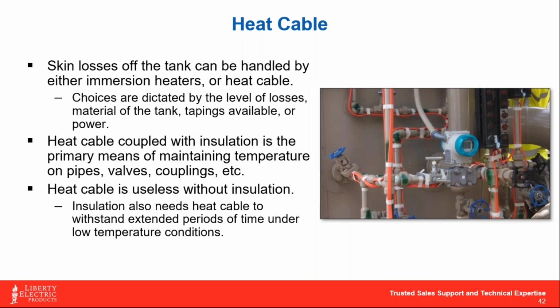And self-regulating cable itself can actually touch against itself without damaging or burning through the cable. So this is a very popular choice that's often used for heat tracing piping systems. And again, what we typically will do is a heat loss calculation to find out how much we have to offset, and then recommend the right wattage cable for that task.